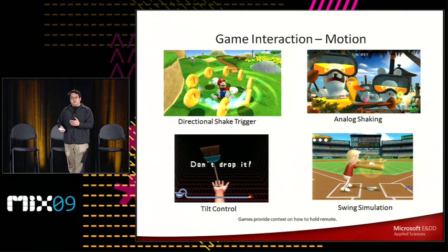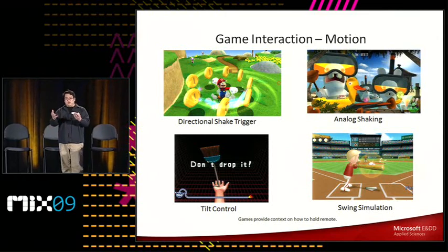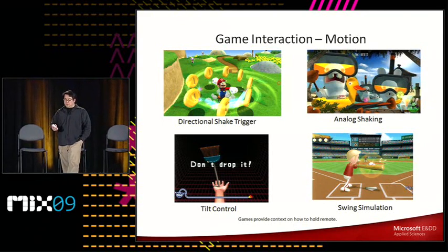You can also do tilt control. We are in a constant 1g acceleration field due to gravity. So if you were in space, an accelerometer would actually show zero acceleration in all directions. But if I'm just standing here, there's actually a 1g acceleration going down, and that's how you can do basic orientation detection with the Wii. It's also what people use on the iPhone accelerometer as well to get orientation of the screen.